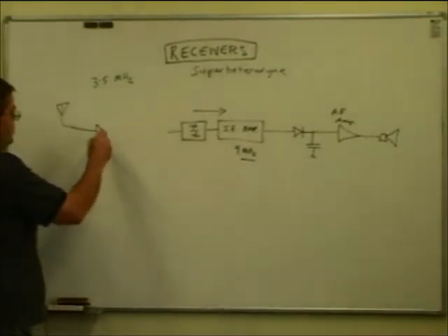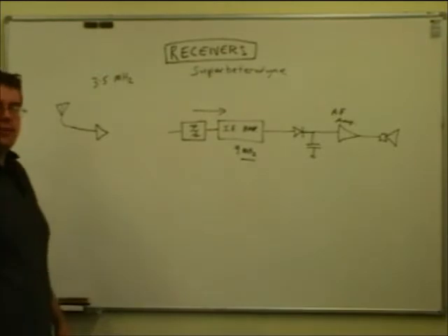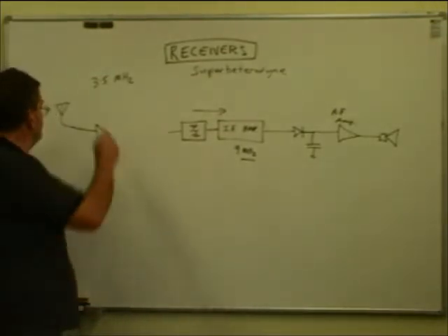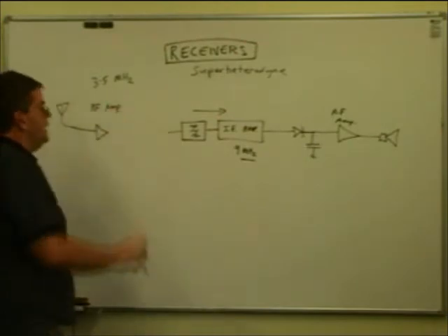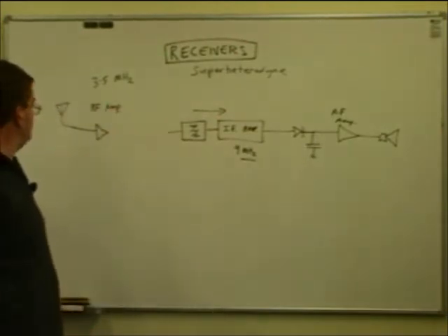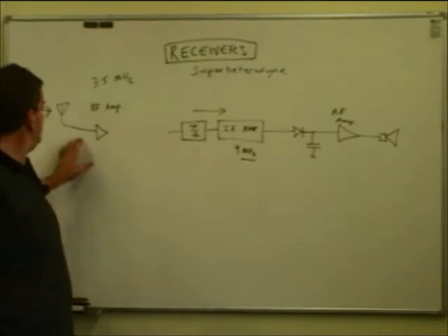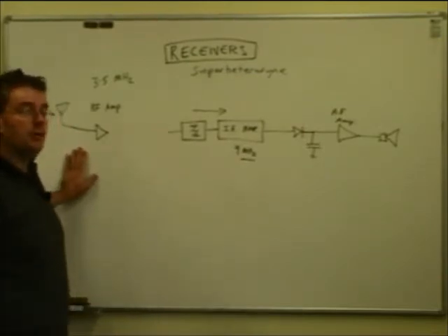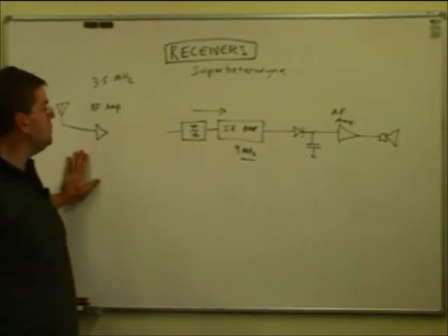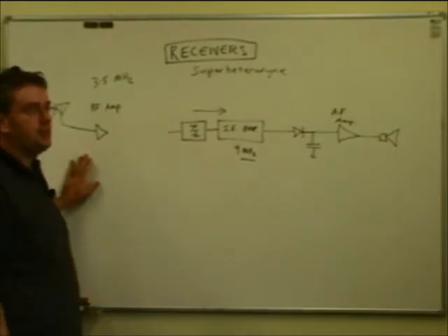and we generally, but not always, put a radio frequency amplifier in here just to provide a bit of amplification at the start of the receiving process. And the reason we do this is that signals here can be very weak. They can be just above the background noise level that's generated in maybe the feed line from the antenna and so on.